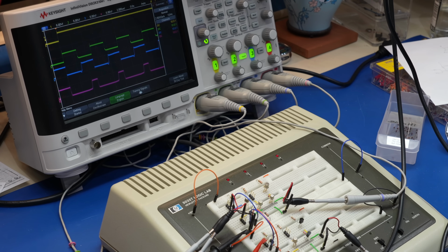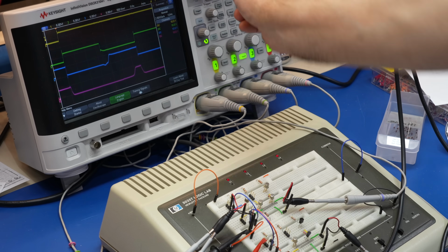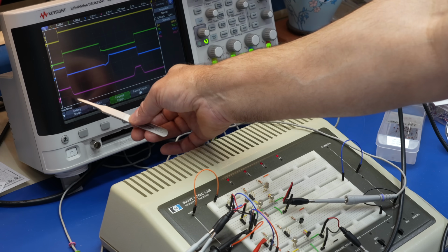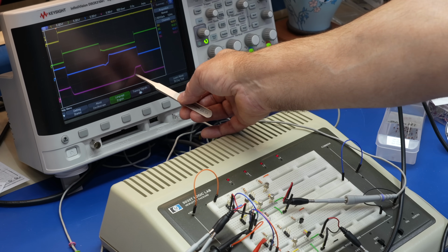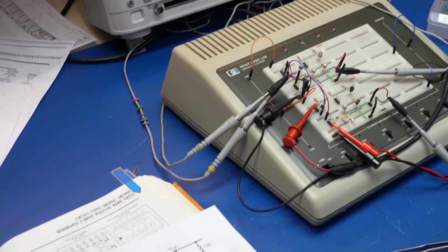We're going to find out why in a minute, but let's first fix our gates so that they at least work at somewhat reasonable speeds. Right now this is 100 kilohertz, so something is clearly not right. There we go, that's a good place to be. The TTL and the DTL are pretty good on the up to down transition, although DTL is slower. There's a huge difference on the down to up. When I saw that at first, I was a bit puzzled.